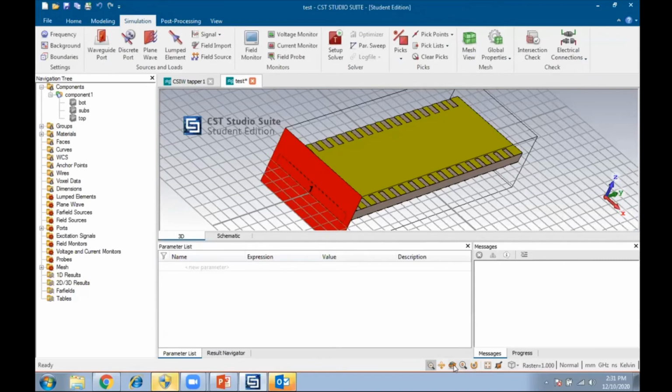Usually a waveguide has two ports, right? Usually my antenna should have only one port, because that's a passive device. So the output must be a radiation pattern. Here it's simply a waveguide. If we short it at this end also and place a slot at this end, it acts as a slotted SIW. That is a different topic. I made the simple one, that is the SIW concept. It's a basic one to build antennas for 5G.